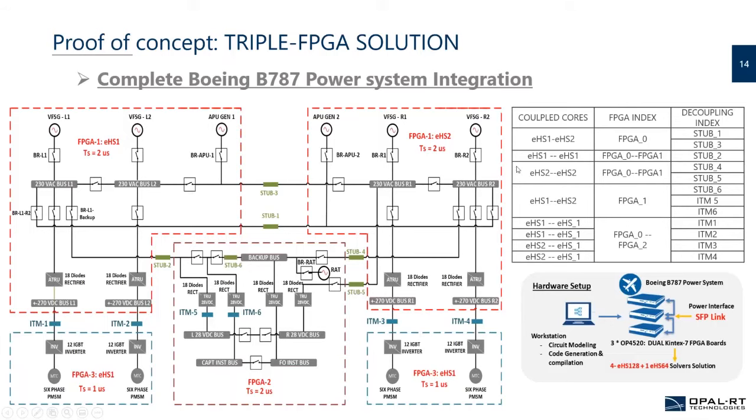So here in this table, we are summarizing the power decoupling element type and also the decoupled node. We use two types of decoupling elements. The first, at the AC side, is the stub line method, and we have 6 power decoupling locations.